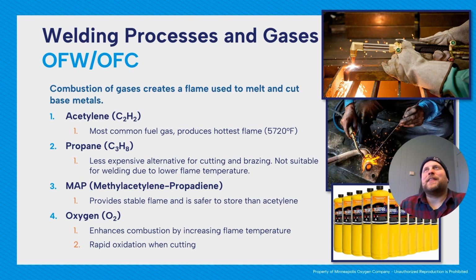It's not the gas that produces the hottest flame, as it says right here, but it's the gas that's most commonly used that has the hottest flame, if that kind of makes sense. Propane, less expensive alternative for cutting and brazing. Usually we're not going to use it for welding because of that lower flame temperature.